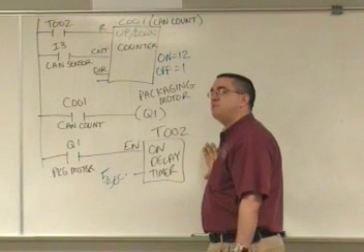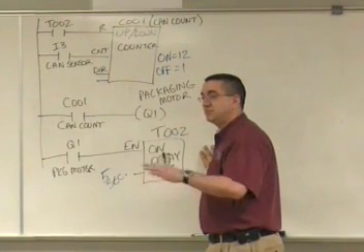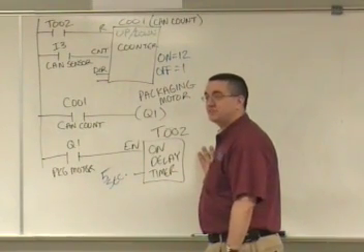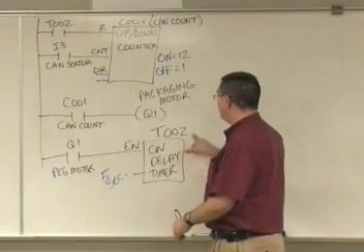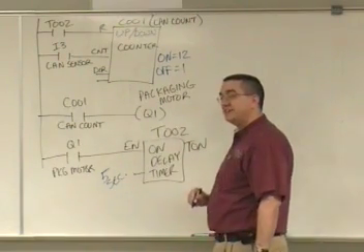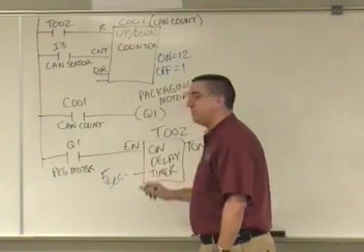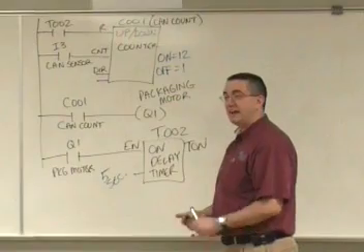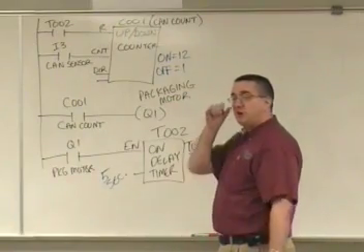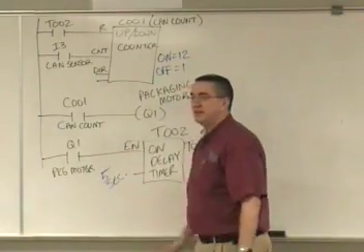And because it's a non-retentive timer, what is this timer going to do when I lose power to it? Stop. It's going to reset. It's going to go back to 0. It's not going to retain its time. If this was a TONR, in this case it's a TON, an on-delay timer, if this was a TONR, I would have another pin here. What would that pin be labeled? Reset. I'd have to manually reset it. But we know with the TON, it's going to reset just upon losing the enable signal.